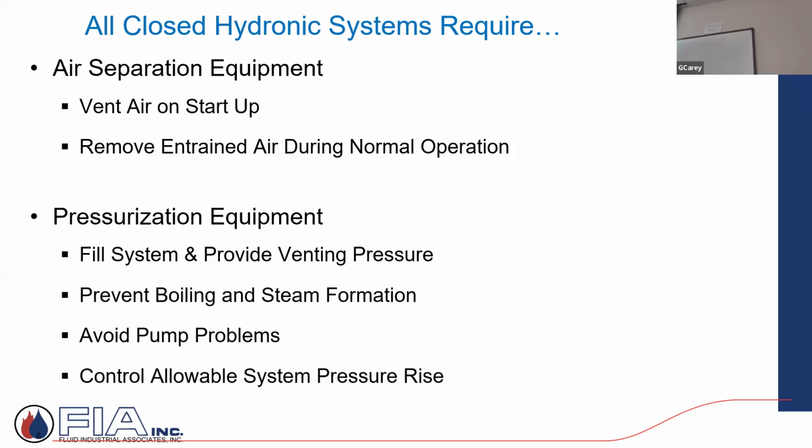So you have a fill pressure, then you have a boiler or boilers or chillers, but they have relief valves, and they have a maximum pressure that their manufacturer says, I don't want to operate at a pressure higher than that. So that's my high side. I have to control it so that as system pressure increases, it never approaches the relief valve setting.